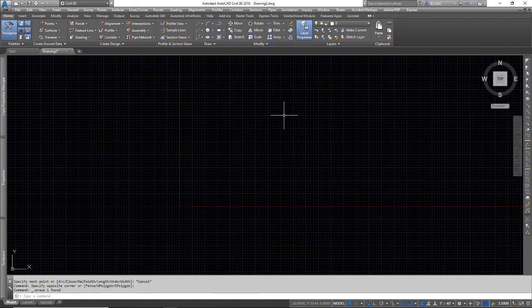And let's say that I want to have my drawing set to those absolute coordinates all the time. So now I can type the system variable DYNPICOORDS, and I'm going to set that to 1. So now I'm set up in the absolute coordinate system, and I'm going to enter that polyline command and start at 10, 10.